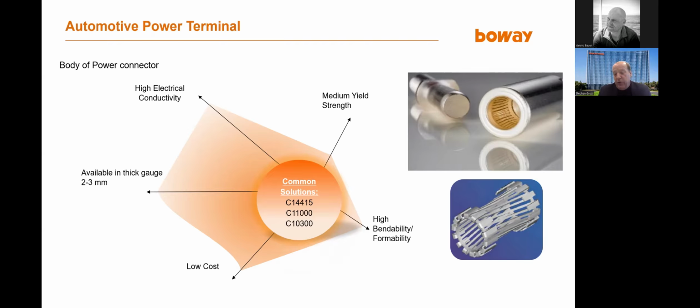Especially due to the weight, the cost item is extremely important. Else, this is driven by conductivity and much less by the strength or formability. Sometimes in the contact zones, due to the high current, we even find temperatures up to 200 degrees C. Again, relaxation is the key then for the inner spring.